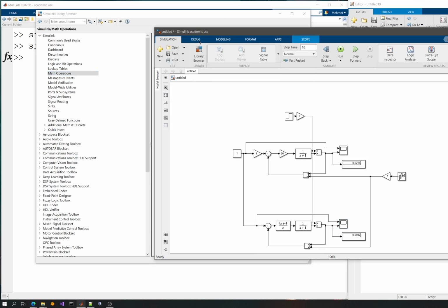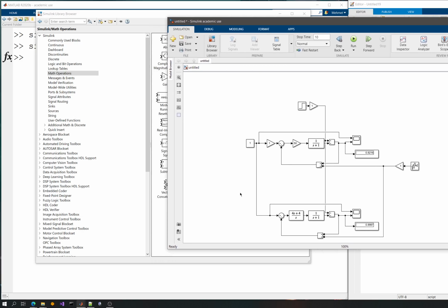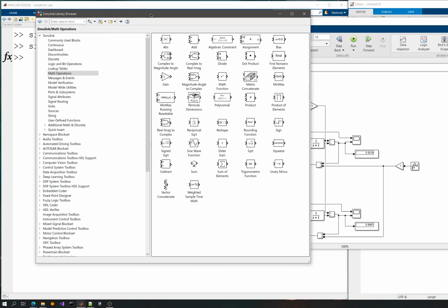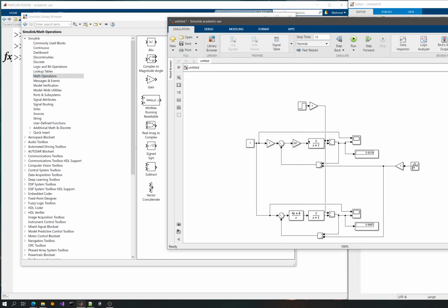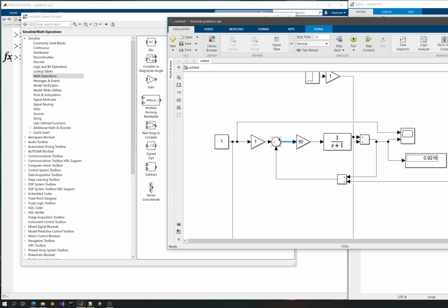The ease here comes from the fact that Simulink is basically a for loop on its own. So it loops through all time instances and uses every value at the time instant that's available. So you are basically bypassing the usage of arrays here. If you have something like 50 here, it will be applied to every element of that array. If we would have used code here, we would have defined this as an array, this single would have been an array.